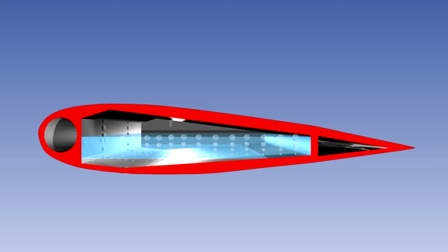The temperature at which a liquid boils will reduce as the pressure on its surface reduces. As an aircraft climbs, the pressure on the surface of the fuel reduces, and with that reduction comes an increased likelihood that the fuel will boil and form vapor in the pipelines. The vapor locks that this effect causes can cut off the fuel supply to the engine, with the result that the engine will stop.